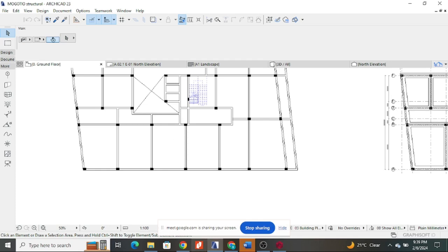I understand, yes. The reason why I was using the walls is because of architectural aesthetics. Because we have the junction between a wall and the slab, at that junction we are supposed to put a beam there. Whether the wall is distributing our load or not, it is good aesthetically, because it will not make sense to have a beam inside the room and then at the junction where I'm having the wall, there is no beam.